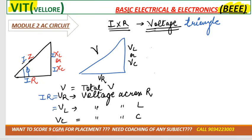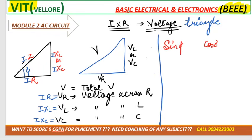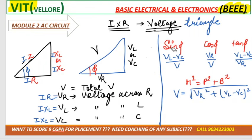VR is I into R. VL is how much? I into XL. VC is how much? I into XC. Similarly, can you get sin phi, cos phi and tan phi and apply Pythagoras theorem as we did in the previous case? So sin phi is this one, cos phi is this one, and tan phi is this one. And by applying Pythagoras theorem, we are getting this formula. Correct?